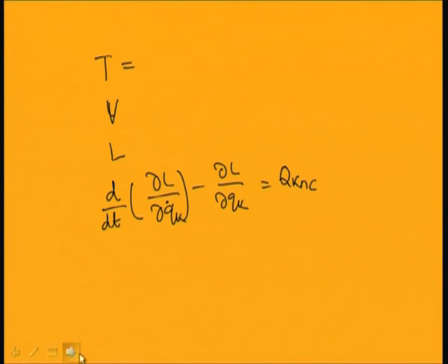Now, till now you know four different methods to find the equation of motion of the system. First, Newton's second law; second, the D'Alembert principle; third, the Lagrange principle; and fourth, the extended Hamilton principle. Generally the Lagrange principle is used for multi-degree of freedom systems and the Hamilton principle is used for continuous or distributed mass systems. So, in most cases for a multi-degree of freedom or 2 degree of freedom system you should use the Lagrange principle or the Newton's or D'Alembert principle instead of going for the extended Hamilton principle.